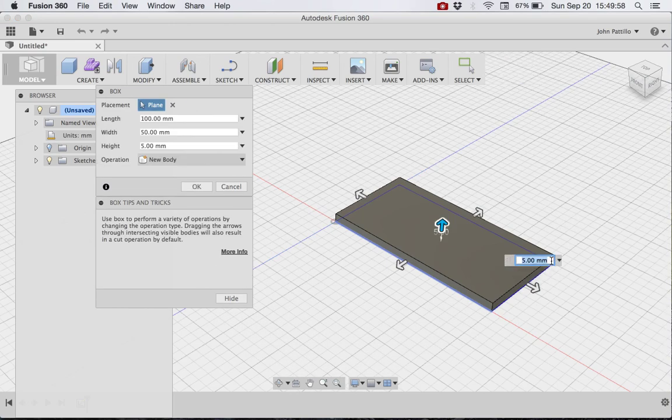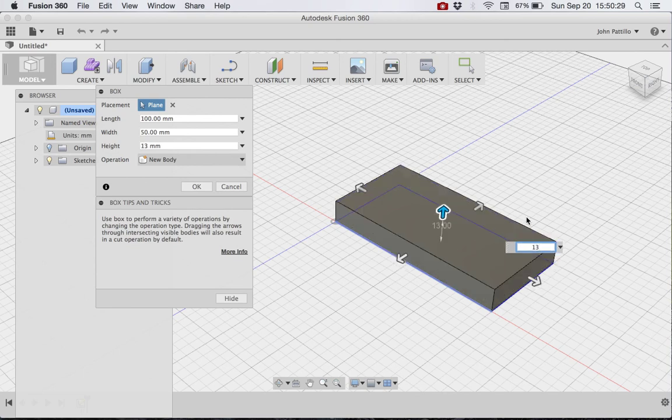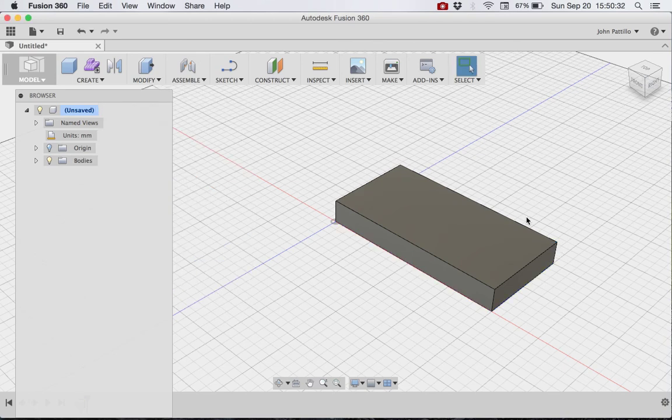Okay. Now the z-axis is where you have to think about it a little bit. I'm using Baltic birch plywood, which is 12 millimeters thick, and I'm going to glue a 2 millimeter sawn veneer onto that. So the total thickness to start with is going to be 14 millimeters. And then I want the x-carve to mill off 1 millimeter. So my final piece will end up being 13 millimeters thick. So that's what I'm doing. I'm building a model of my final piece. Okay, so that's that. Now that's all I need to do since this is such a simple thing that I'm building here. Just a little sample of veneer.